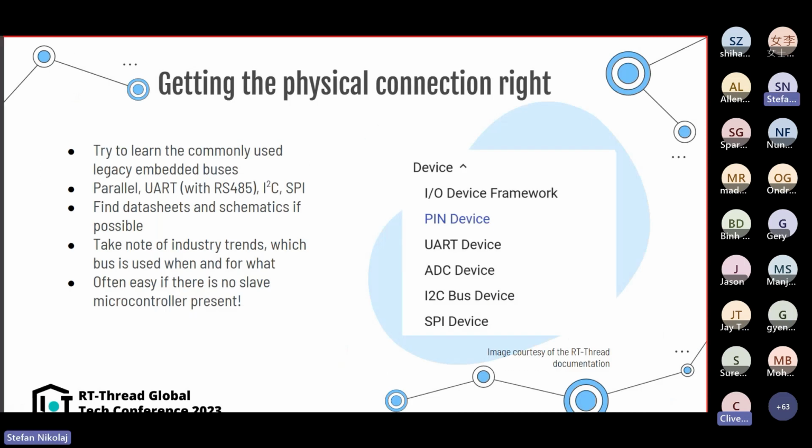So in both of the examples I provided, the synthesizer and the PLC, the peripherals utilize a parallel bus that incorporates signals for chip select and read-write operations. This type of bus is very commonly found in older systems, but is less prevalent in newer ones, which may employ different communication protocols. Usually, you will see in the PLC world things like Ethernet, different Ethernet protocols, Modbus. I've seen CAN, and of course RS-485.